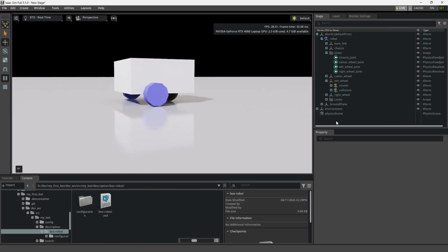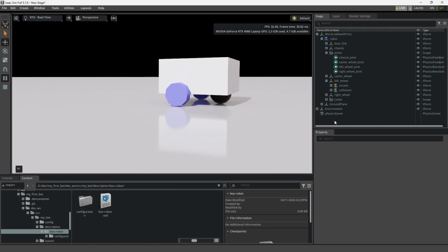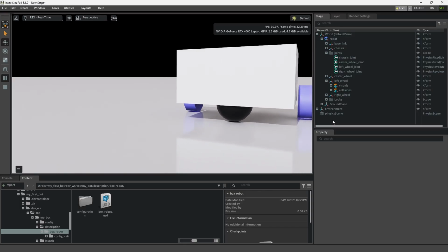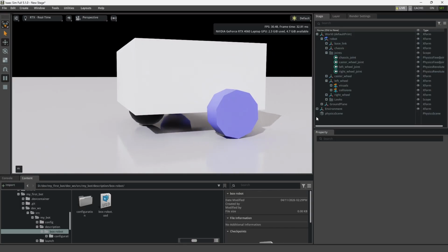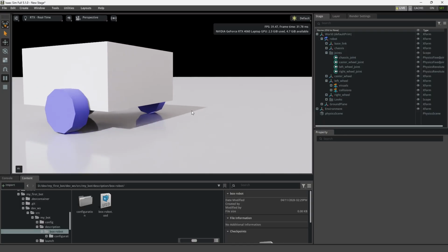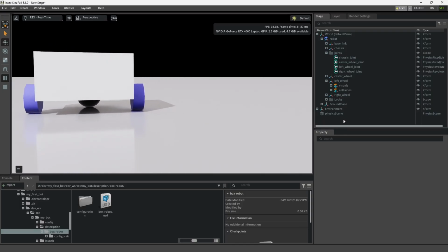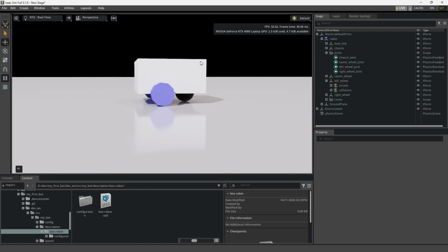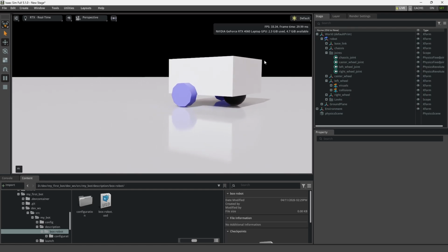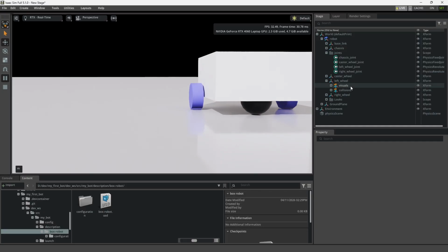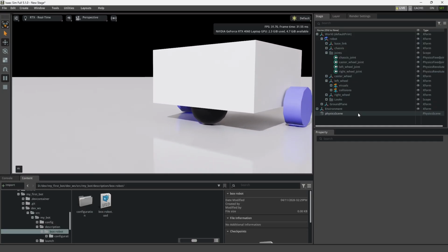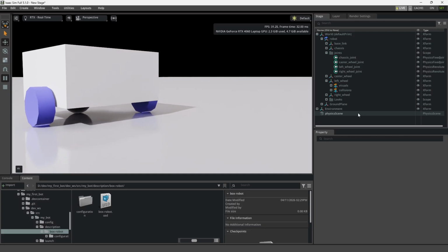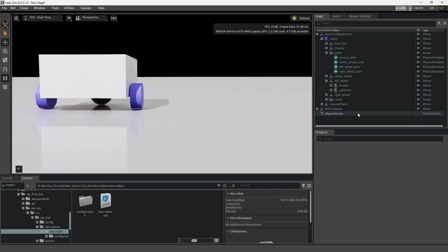We'll click off of this so that you don't have that in the way. And that's pretty much it. That's really all we're going to do in this particular project, was just more or less get this thing imported. And you can see once the wheel goes away, it feels a little wobbly, but once the wheel's kind of hidden, you can see that the robot is actually quite stable. It's running, my mouse is not, but the robot's stable, as the collision mesh is the thing that's doing the calculation, determining where the robot hits the ground.